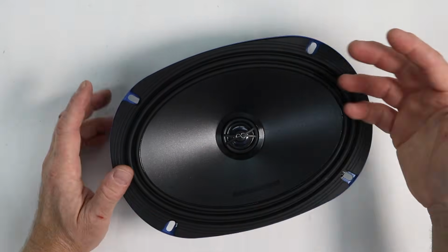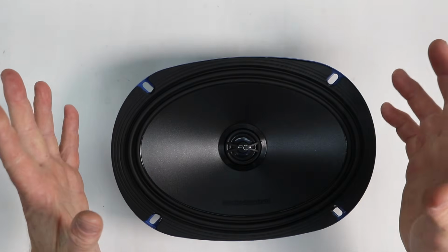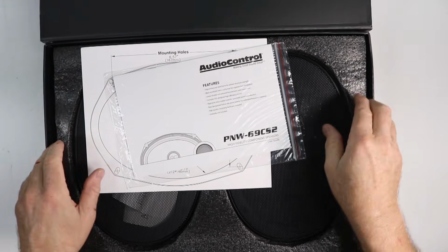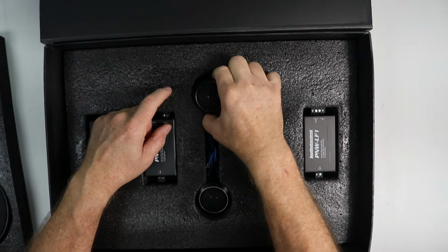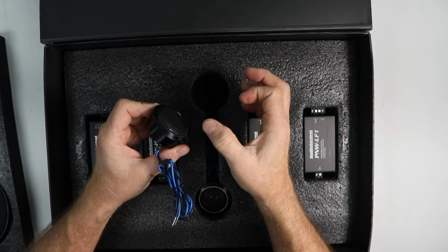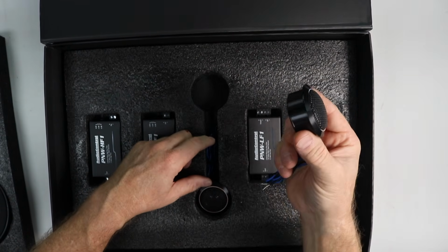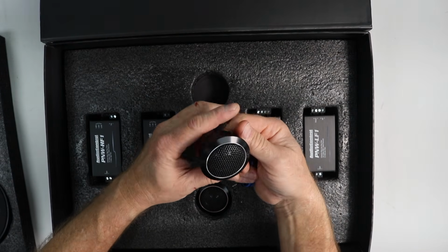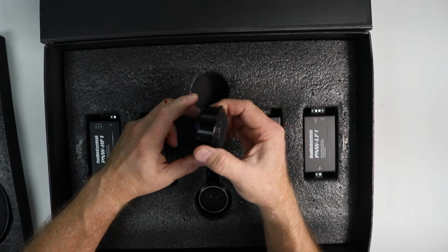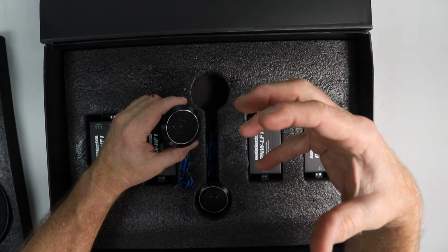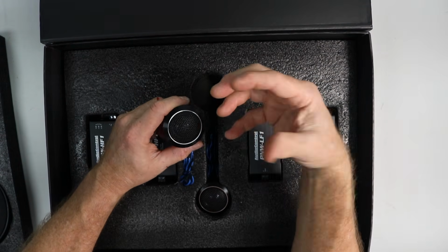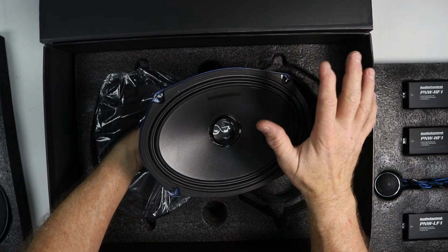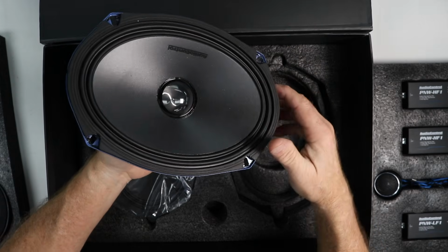There's nothing you have to set up. You just have to connect power to this. It's passive. As time went on, components became all the rage, meaning you have a tweeter that was no longer mounted in the middle of the driver or suspended over the driver. It was a standalone thing. The car manufacturers started putting tweeters in the dash, in the sail panels, in the A-pillars, because tweeters are very directional. The higher up and closer to your face you can get them, the better you'll hear them. And the mid-bass drivers, lower frequencies, not so directional, would stay down in the bottom of the door.